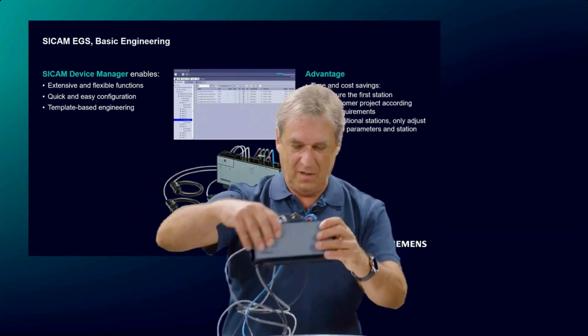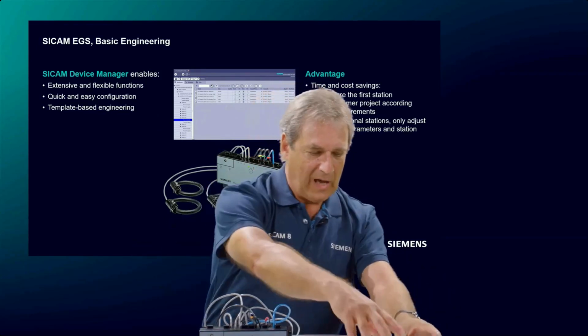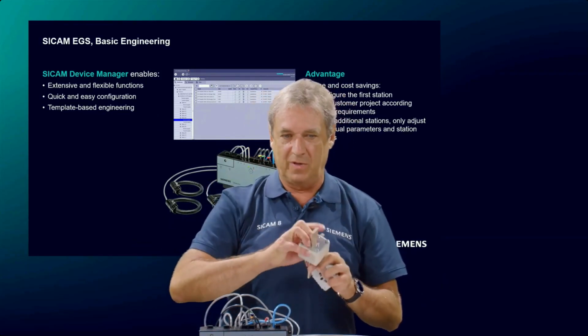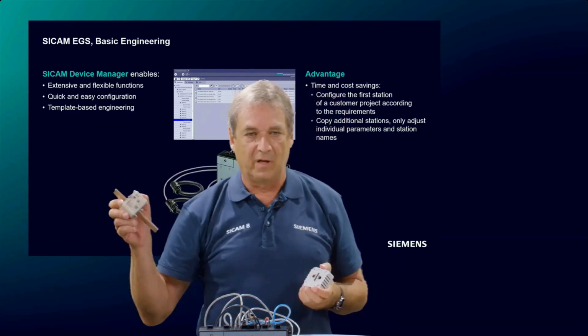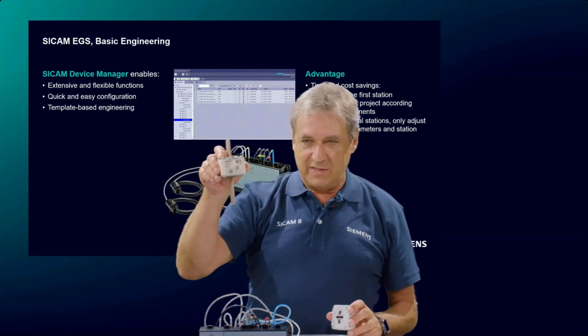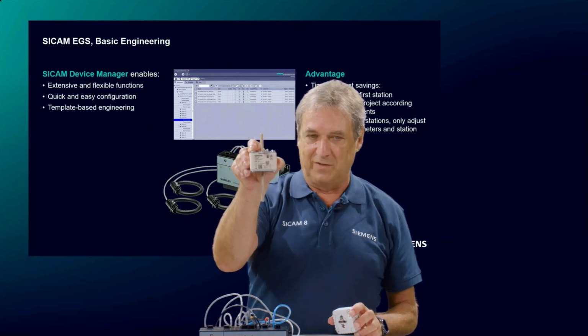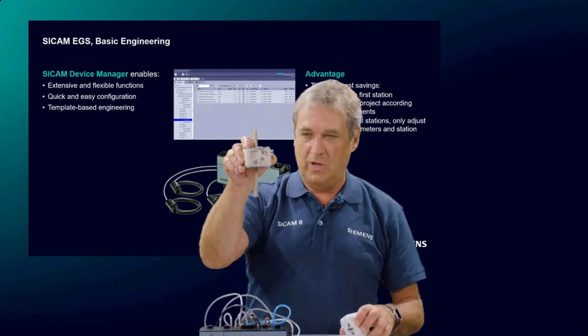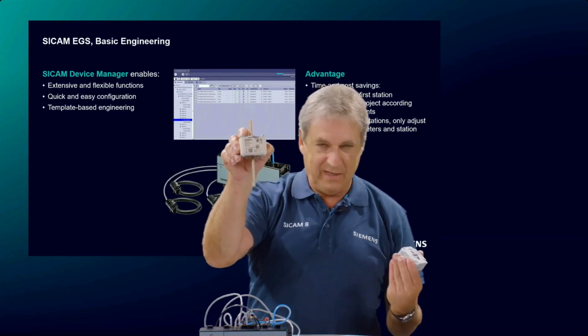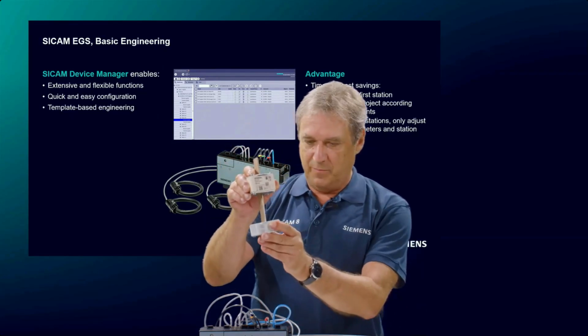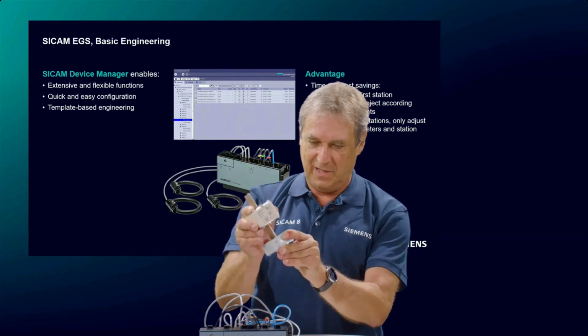But I also explained it before, our solution goes one step beyond. And now we are coming to the 3NA smart fuse. This is the real fuse part. As you can see, it's compatible to an NH2 version. And here comes really the highlight. I can put this communication part here on the shaft.